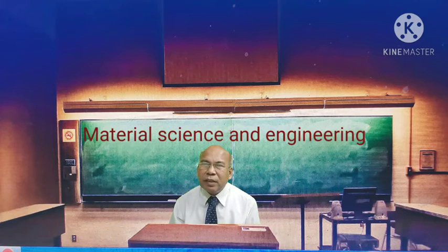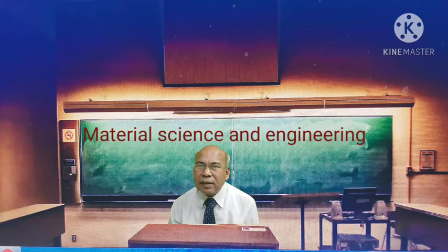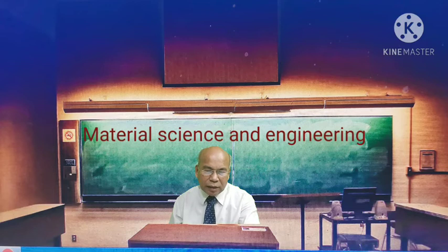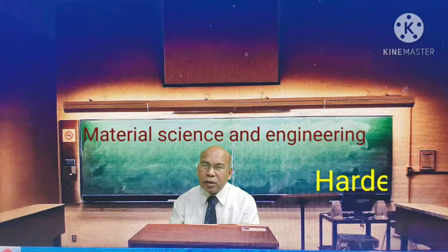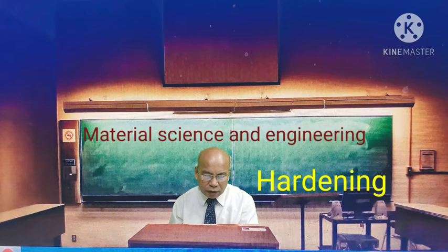In the case of the annealing process, the metal should not be taken out of the furnace immediately after heating. It must be cooled in the furnace itself just by switching off the furnace. But in the normalizing case, the materials are removed from the furnace after heating, and they are kept in the airflow. So the flow of air removes the heat gradually. In this normalizing process, machinability is mainly improved, and this method is economical and suitable for large castings and forgings.